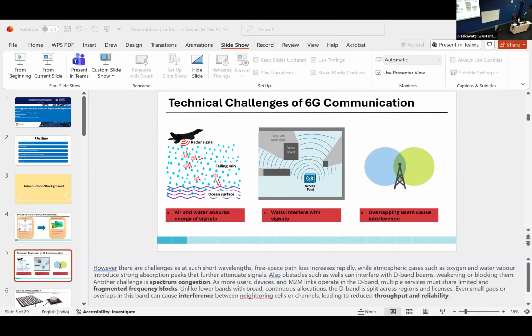And this is crucial since small geometric or material imperfections could shift the resonance. And then finally, the ultimate goal is to create a real-time coded metasurface where each meta-atom can be a diode state represented with binary numbers. And then these binary controlled patterns can dynamically block or redirect electromagnetic waves, paving the way for smart surfaces in the future 6G communications.